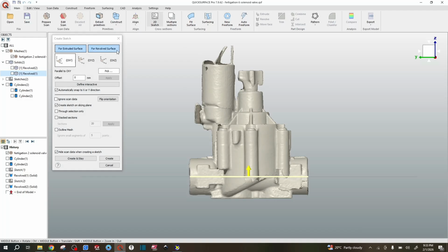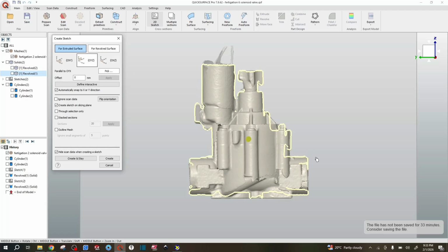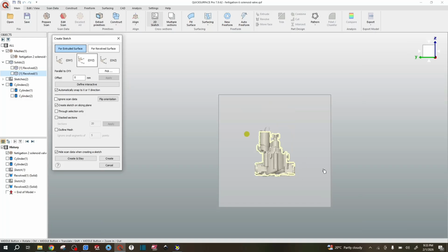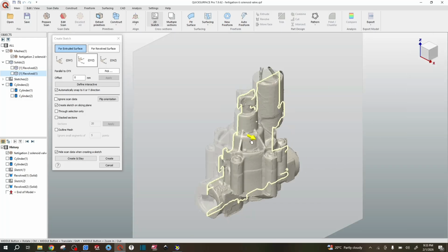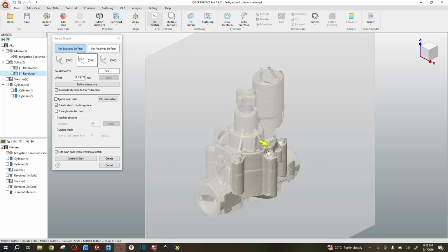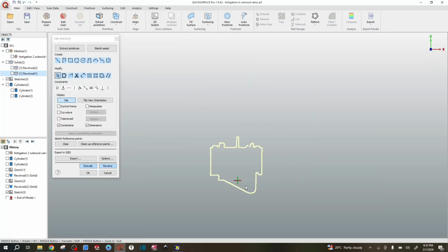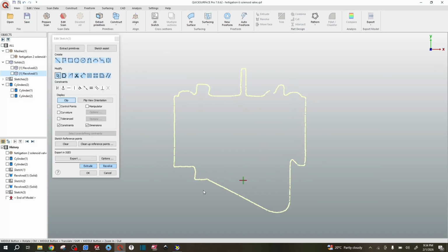So for this 2D sketch, we're going to use the YZ plane. Yes. So, and on this YZ plane, let's just put it in isometric. And we want now to, you remember the big cylinder that I said we're going to cut? That's what we're going to do. We're going to create a sketch that is going to help us to create this thing.